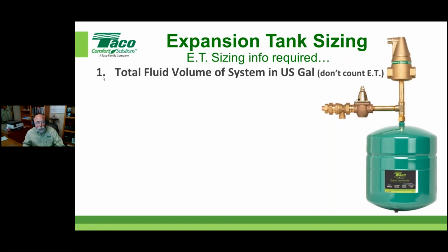Okay, so number one, and very important, and number one typically is the hardest thing to achieve a lot of times, only because people do a lot of guessing. They do a lot of guesswork, but we need to know how much fluid is in the actual system. Again, I'll point out that we don't care what the expansion tank holds. We just care what's in the system itself. That's the pipe, the valves, the fittings, that sort of thing. The boilers, the air separators, all that good stuff. So anything that's going to be full of fluid under a static condition, okay?